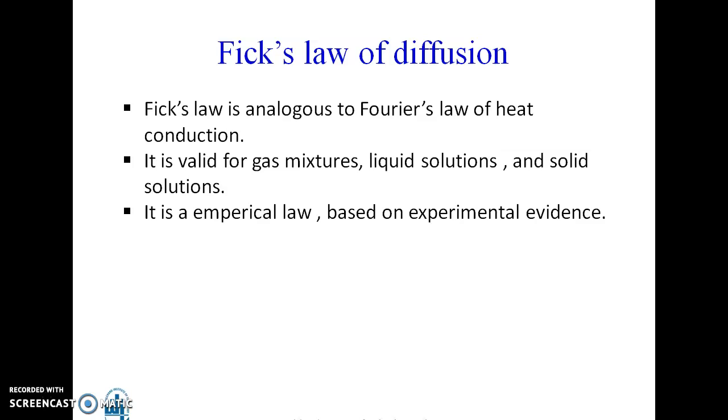Now, to study mass transfer, we have Fick's law. Fick's law is analogous to Fourier's law of heat conduction. For conduction, Fourier gave the empirical relation Q by A is equal to K dou T by dou X. This was Fourier's law of heat conduction. Similarly, to study mass transfer, Fick suggested an empirical law.